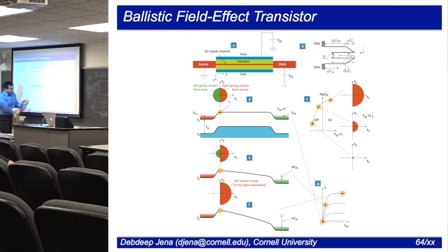This will become shrunk. And now everything is going to the right, right? And once you reach this situation, you can see that now I can apply more drain voltage, but nothing's going to change anymore, right? The shape will remain like this because the drain is not doing anything anymore, right? Is that clear? Once you reach the situation, it's one half circle to the right, and you apply even more drain voltage, it remains like that, right?